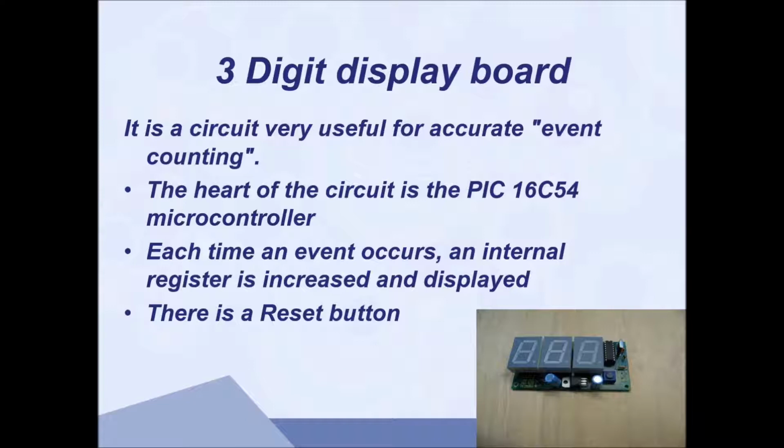Our first board is the 3-digit display board. It's a circuit very useful for accurate event counting. The heart of the circuit is our PIC16C54 microcontroller. Each time an event occurs, an internal register in the PIC is increased and displayed, and there is also a reset button.